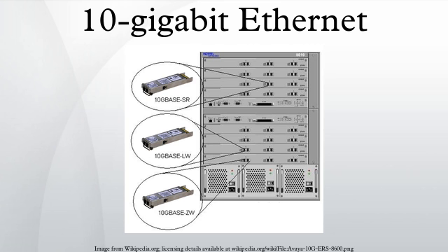The auto-negotiation protocol selects between 1000BASE-KX, 10GBASE-KX4, 10GBASE-KR or 40GBASE-KR4 for operation. 40GBASE-KR4 is defined in 802.3ba. New backplane designs use 10GBASE-KR rather than 10GBASE-KX4.